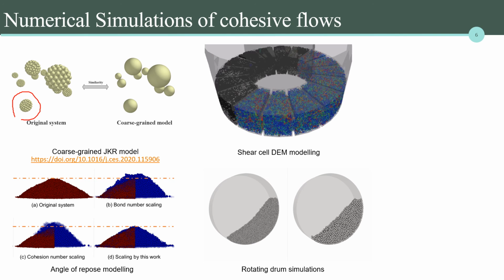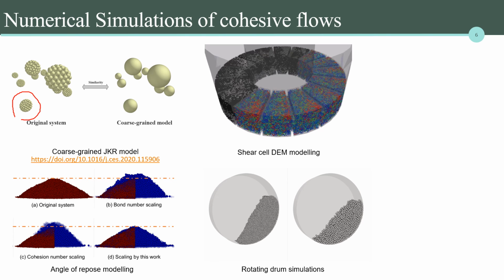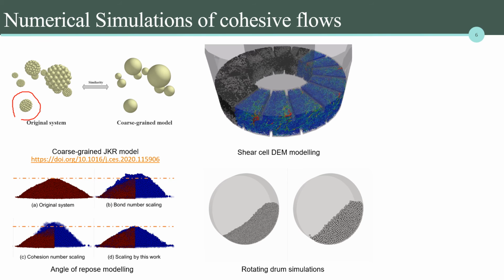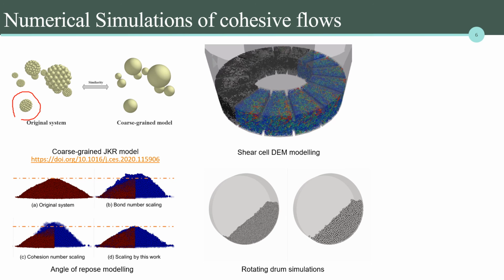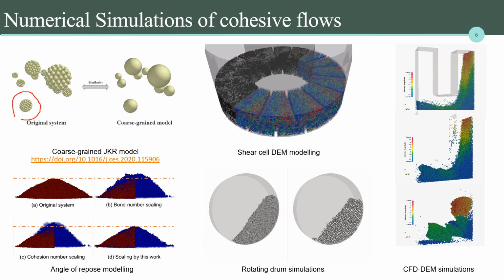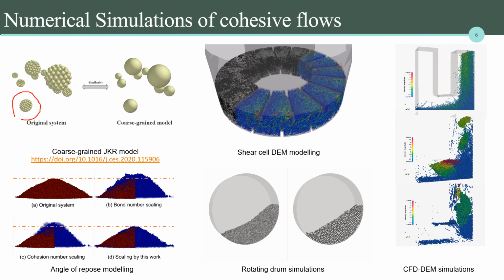So after calibrations, we can use the coarse-grained DEM simulation to study different processes, like studying the particle mixing in a rotating drum, coupled with CFD simulation to study the fluidization and entrainment of the cohesive particle flows.